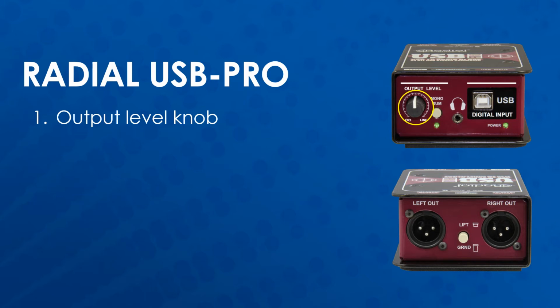It is recommended to turn this fully clockwise when setting the input level on the mixer so that a user can't turn it up when it's not expected. Along with this, it's also recommended to run the computer at 100% volume as well.